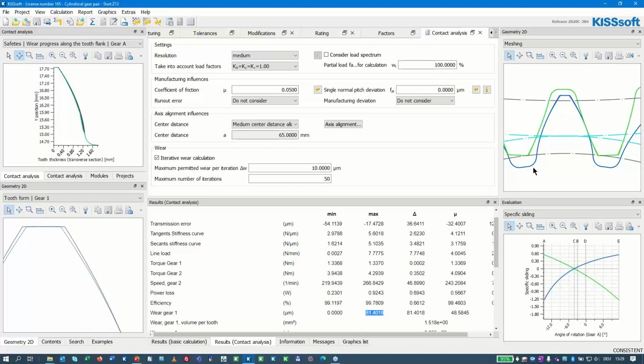It's independent of a tool that you would use in, say, hobbing of a metallic gear. This means that for plastic gears, but also, for example, for forged gears or sintered gears, the root stress calculation as per the gear rating standards can be inaccurate because the root shape is not matching the root shape that is used in the theory.